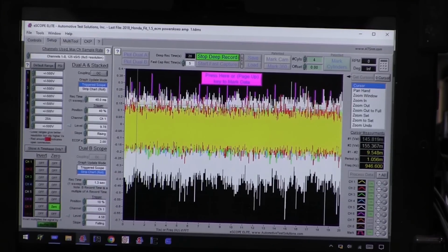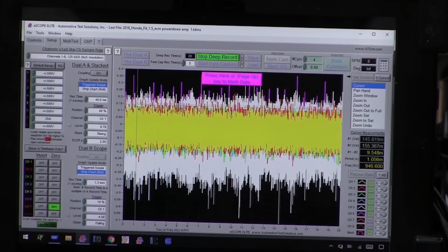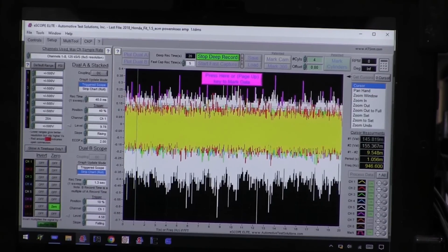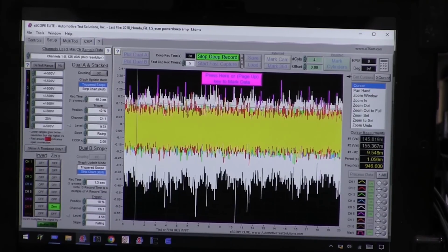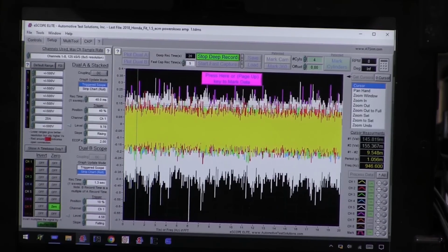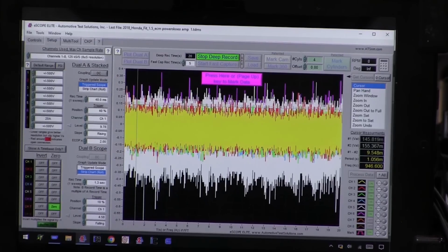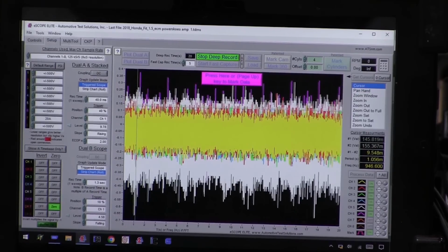Don't get confused, because this is just a motor that's being controlled very rapidly, and you always have some noise off these motors. And apparently this ground has to do with that throttle circuit. I can already see it because I can open and close the throttle, and I can see it change the noise level.